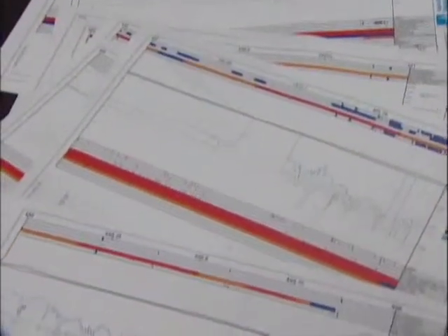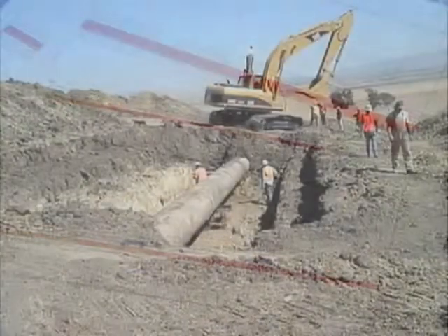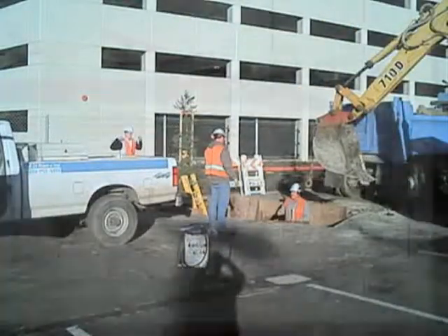Scheduled indications are of lesser concern, however, could still represent conditions where corrosion may be present or may occur at some point in the future. As a minimum, one scheduled indication must be directly examined. Monitored indications are those that have the lowest likelihood of experiencing corrosion activity and are monitored for review during future assessments.